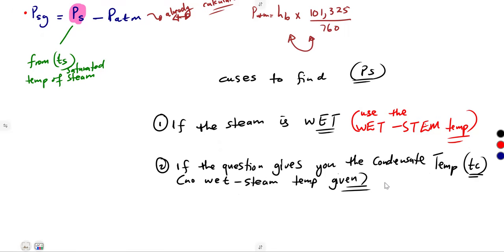Do not just use it anyway. Just like we saw this one, guys. It's not the first time. Remember, I talked about this when we dealt with the pressure before, when you are calculating that HS, when we wanted to calculate H wet. And we said it must be taken from the temperature of the steam, which is from TS.